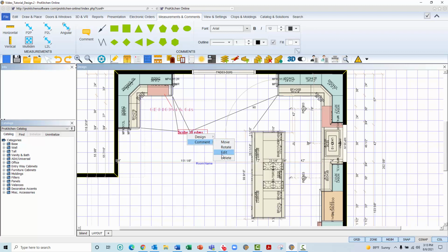To utilize the Rotate option, right-click on the comment, select Rotate, move your mouse, or type the desired angle in the info panel to the left, and then tap Enter on your keyboard. In a line's right-click toolbox, you can choose to move, change start, change end, delete, add arrow at start, add arrow at end, both of which will become remove arrow once added, and attributes.